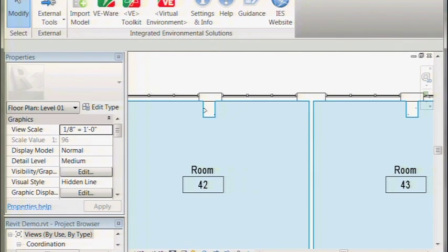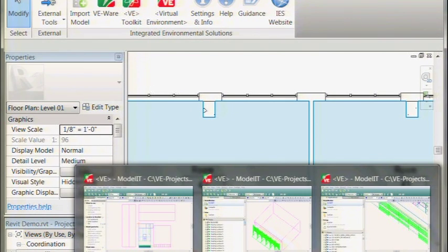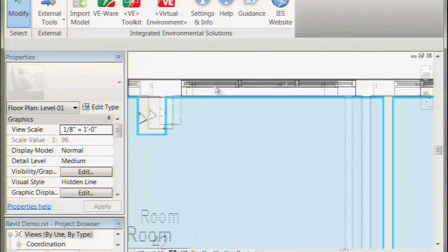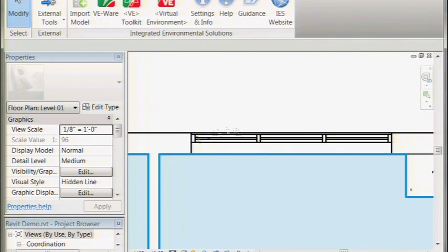So inside of the virtual environment, if you're just doing thermal analysis, you're probably not going to use your inner volumes so much, or maybe standard-wise in your office you've decided to only use inner volumes. But in the virtual environment, you always have inner volumes defined. So even with Revit models, only with Revit. When you bring it in from SketchUp and you do a thin-walled model, your inner volumes are not defined.